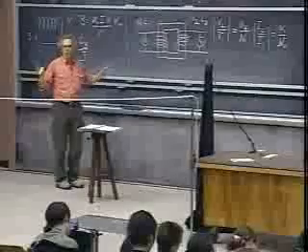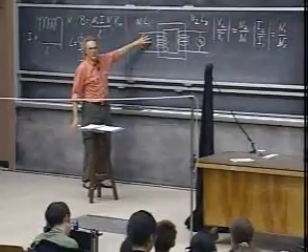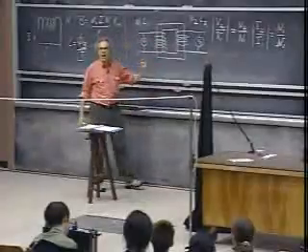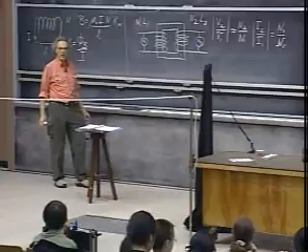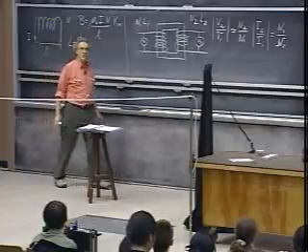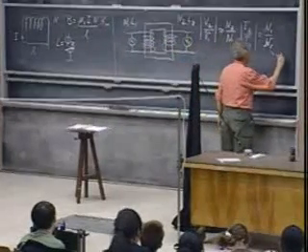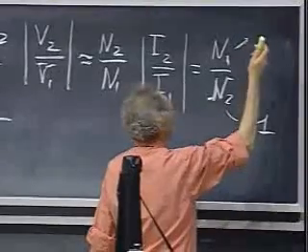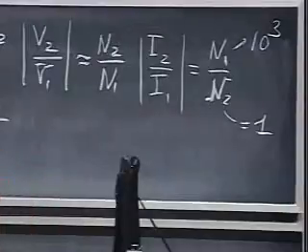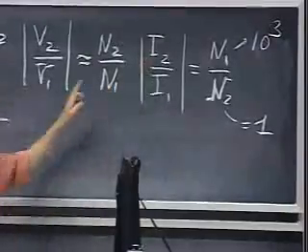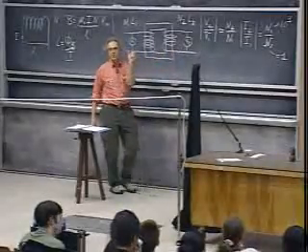It only can work approximately, and I mentioned that on the side in my lectures, if the resistance here and the resistance there is way, way smaller than the value for omega L. And we did try to achieve that during one of the demonstrations that I gave on this. I remember we had the induction oven, whereby N2 was 1, and N1 was very large. I don't remember what it was anymore, but it was of the order of several hundred, maybe 1,000. And we managed to get a current in the secondary which was huge, which was close to 1,000 amperes. It was enough to melt that iron nail.